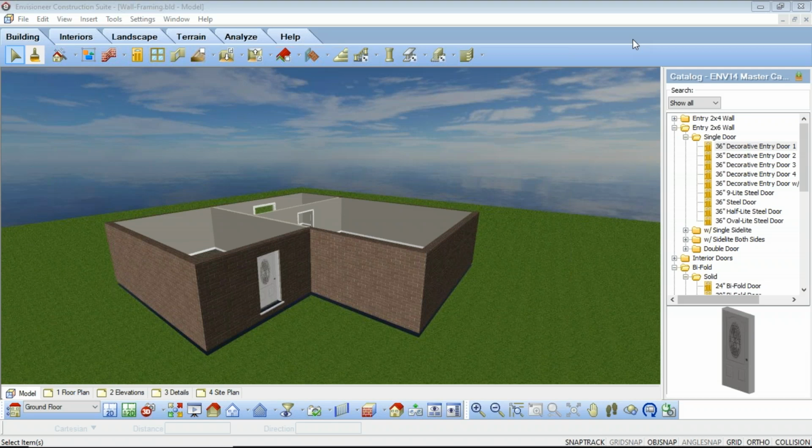First we want to talk about our wall framing. Every building location in your project has a number of framing options assigned to it that determine how the walls on that location will be framed. These options include your span tables, which determine how your openings should be framed, your infill, which is your stud, top plate, bottom plate configuration, your framing rule, which is the direction in which your walls are framed, and an intersection lookup table. This determines how your intersections are going to be framed as well.